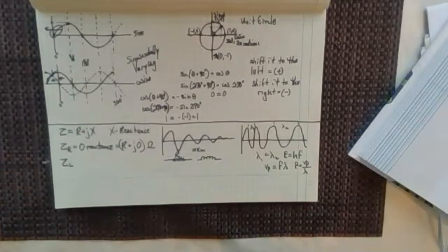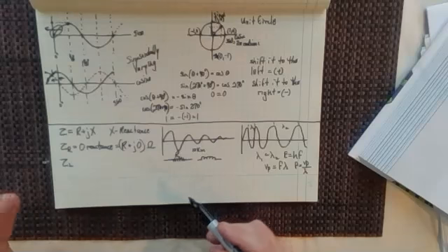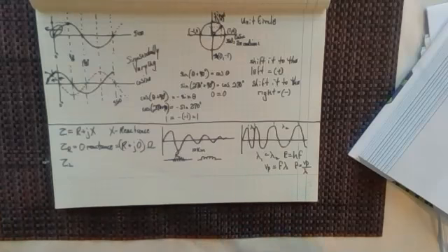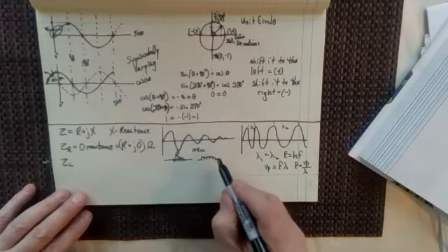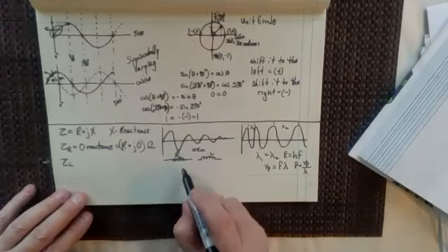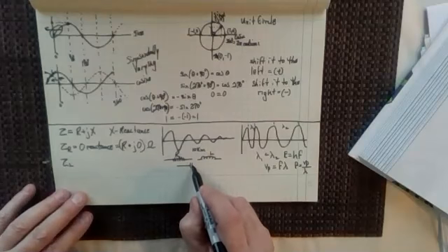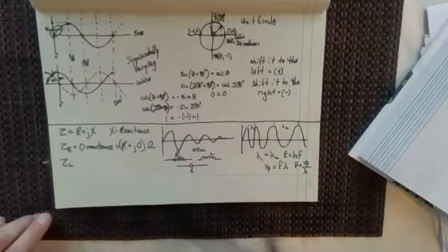That's to help with the magnetism, because the high permeability of electrical steel allows a greater magnetic field to be created by the inductor instead of having a hollow air core. The difference in relative permeability between electrical steel and air can be almost 10,000. So that's an inductor anyway. And then, of course, the capacitor, which is two plates, and that's very descriptive of what a capacitor really is.